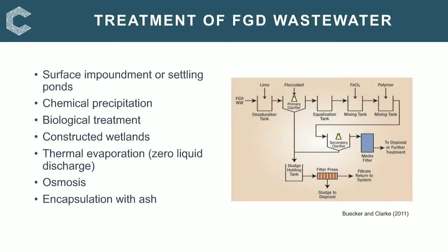Right, the discharge limits set by the European Union and the 2015 emission limitation guidelines in the USA are based on limits achievable with best available techniques, or BAT. In the USA, the BAT technologies are chemical precipitation followed by biological treatment for existing power plants. And for new power plants, the technique is evaporation.